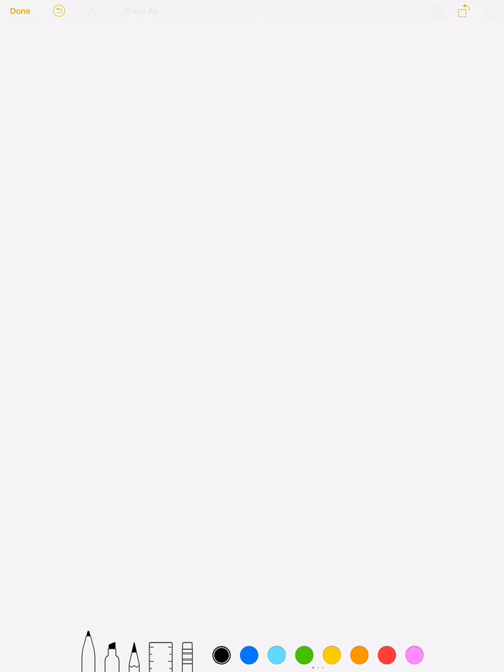Moving down to part B, here we have, again, 4 braces, but they are on the perimeter. The braces A and C are the ones that are active for load that's left and right. So our drag strut elements are any beams or girders in line with the brace A and the frame C. I called it a brace before, it's really a frame.